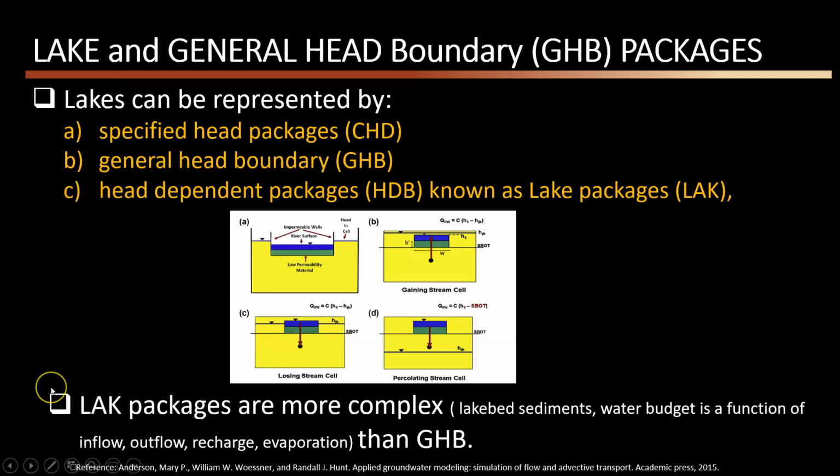Okay, lakes are the other hydrological elements that we usually want to consider in our groundwater modeling. So there are multiple ways to simulate the impacts of lakes on our aquifers. One is to use the specified head package. This is pretty much like the river package. The lake concept is very similar to the river discussion that we had.